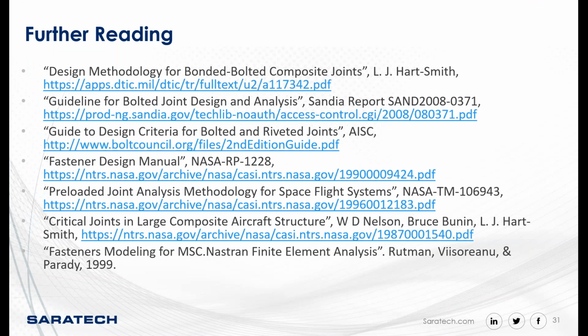Perfect. And then the next question is, element perpendicular to plate is a K6ROT issue. Can the CFAST use more than one element per side? Yes, it can use as many elements as you want. Well, I take that back. It's basically on the diameter. So it's typically, depending on your mesh size, going to grab one element. But if you mesh it fine, it'll grab multiple elements. And yes, that's a good point, because you don't have that stiffness in the drilling degree of freedom. And if you have an element that's normal to it, then you run the risk of it having a singularity and rotating.